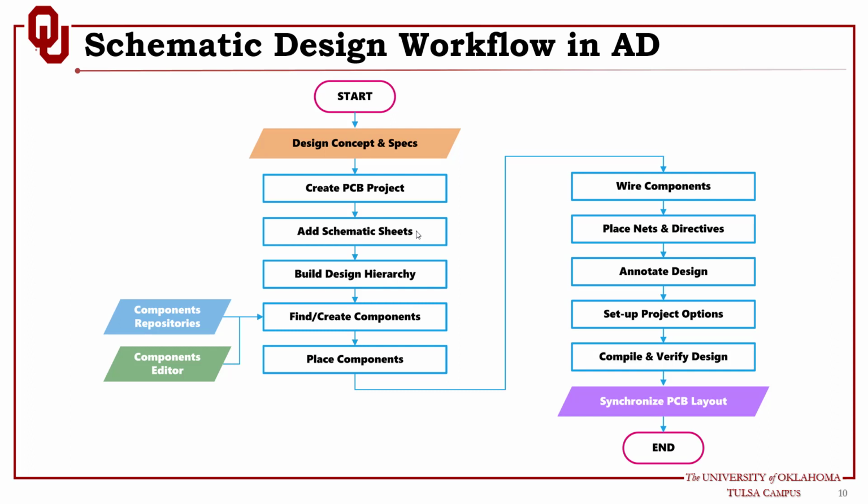And before we do that, let's do a review of the schematic design flow, because this is what I use all the time when I create a project. As we said in a couple of sessions earlier, you always start from the design concept and specs. You need to have specifications for the project you are designing. You create the project, add schematic sheets, build the design hierarchy, and again, if you have a template for the project and schematic sheet, you don't have to create these.